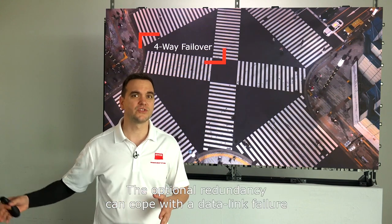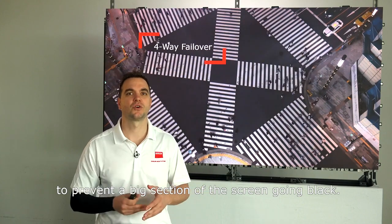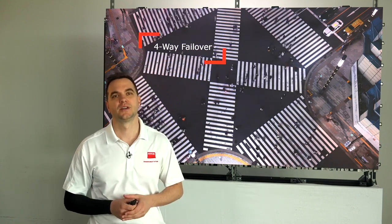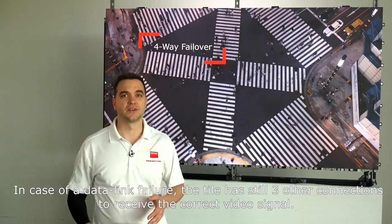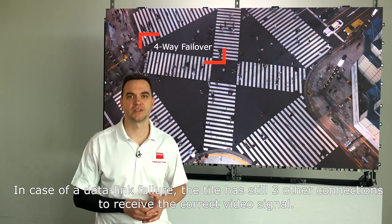The optional redundancy can cope with a data link failure to prevent a big section of the screen going black. But this redundancy mechanism can only cope with one failure. The new receiver card of TruePix connects every tile with the 4 tiles surrounding it. In case of a data link failure, the tile has 3 other connections to receive the correct video signal.